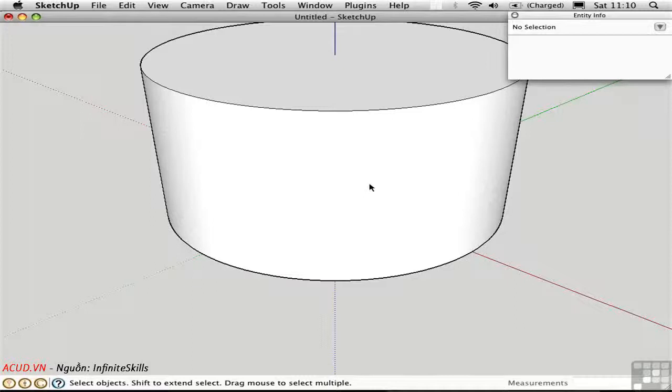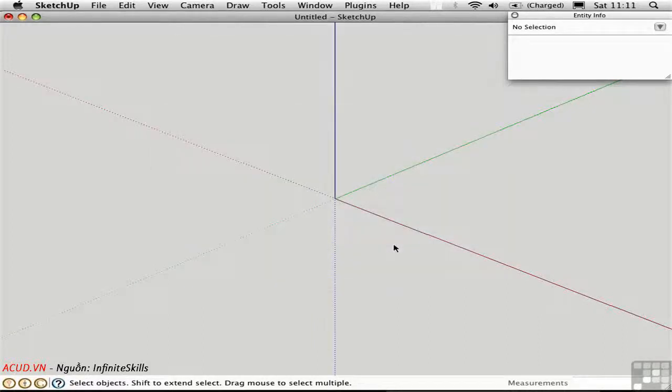It's very important that you balance the need for smooth curves with the need to be efficient when you're modeling. And so you just want to have as few segments as possible to convey the idea of a smooth curve. So for a circle, 32 is a good number. It depends on the scale that you're looking at it, though. If you're creating a rotunda that's round, you might need more segments. If you're creating a profile for a handrail, you might get away with 8 segments or 16, something of that magnitude.